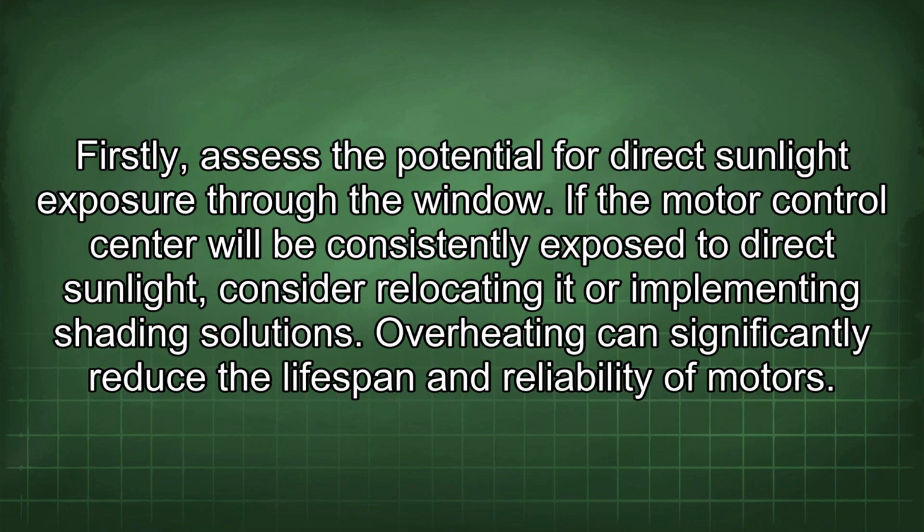Firstly, assess the potential for direct sunlight exposure through the window. If the motor control center will be consistently exposed to direct sunlight, consider relocating it or implementing shading solutions. Overheating can significantly reduce the lifespan and reliability of motors.